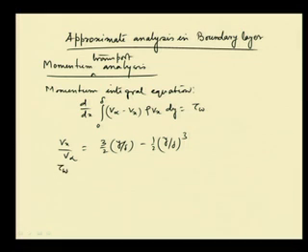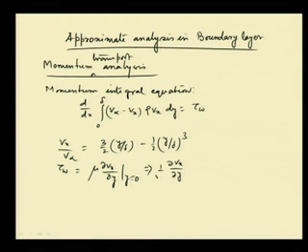Now, tau w is equal to mu into del Vx by del y at y equal to 0. This is Newton's law of viscosity, and tau w is the wall shear stress, which happens at y equal to 0. So, if we do this, 1 by V infinity del Vx by del y is equal to 3 by 2 into 1 by delta minus 3 by 2 into y square by delta cube. That is coming from this equation.